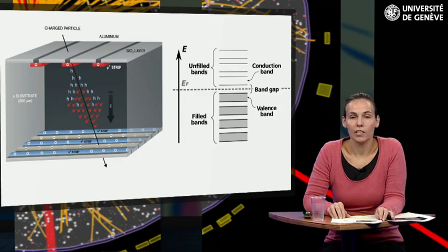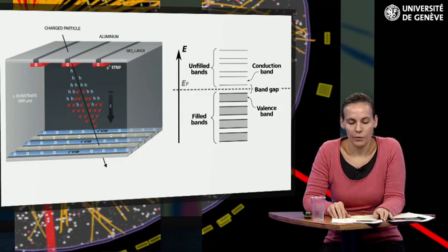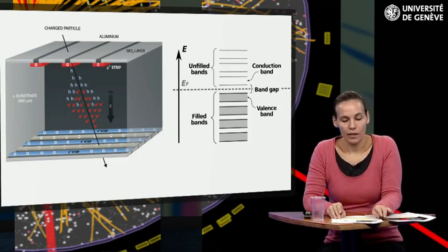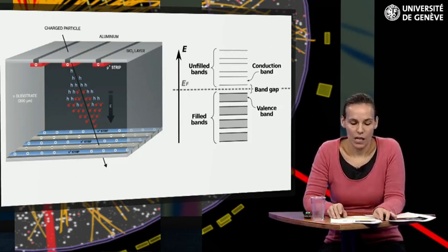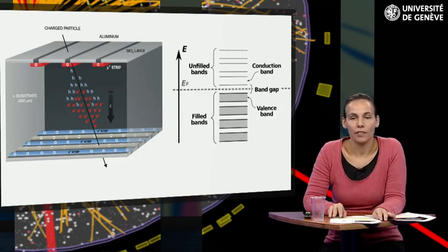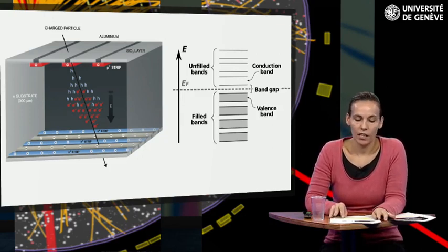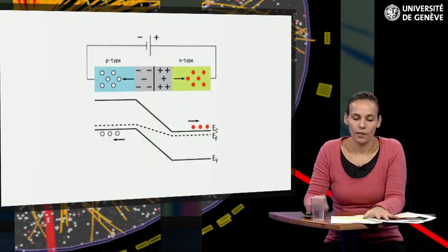Semiconductor detectors have very good energy resolution. They are compact since they are made of a solid. They are thin, with a required thickness much smaller than the radiation length. The spatial resolution is of the order of micrometers, ideal for tracking detectors. And they also produce fast signals. However, they are expensive, they are fragile to mechanical, chemical and electrical impacts, and their performance is degraded by irradiation.